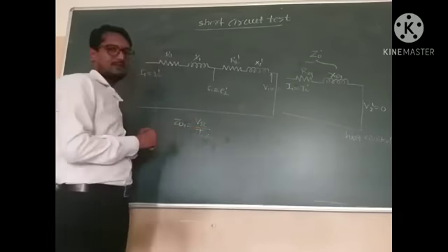After that, we know that W, or WSC, is nothing but the total copper loss. Therefore, we can write W equals I square R, that is, W equals I1 square R01. By using this we can also write R01 equals W upon I1 square.